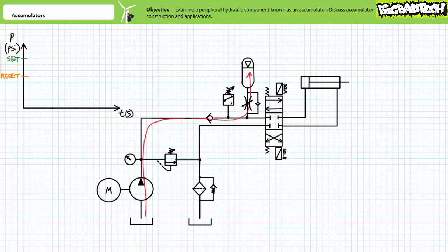During idle time, the pump can charge the accumulator, and when pressure has reached a predetermined value, as dictated by the set value of the pressure switch incorporated on the pressure line, the pressure switch can be used to turn off the motor-driven pump. This prevents the pressure relief valve from being actuated and the motor-driven pump from being run, both scenarios essentially wasting energy.